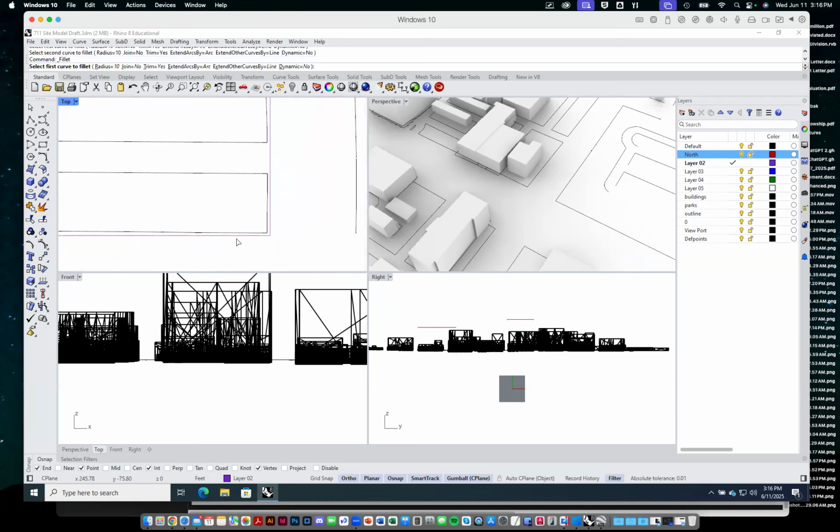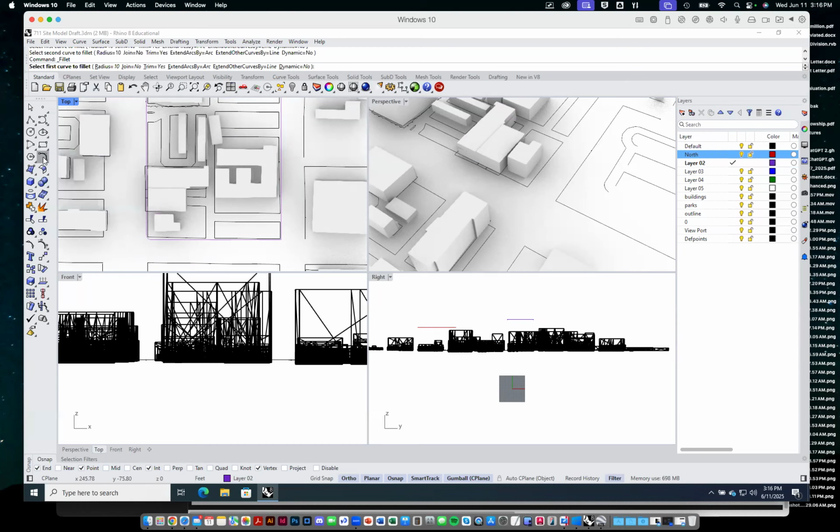So that's what this fillet command is. It's right here, fillet. So again, think about this toolbar. We have points. We can make points and we can make curves and we can make surfaces. But we also have a set of tools down here at the end of the curves. Once we've made curves, we can begin to modify the curves and do interesting things with them. Things like fillet, chamfer, trim, intersect, extend. We can project them in different ways, etc.